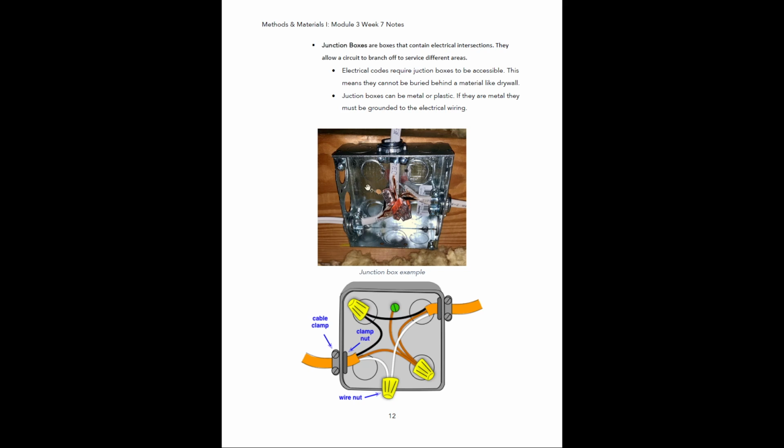So when you're all done wiring this up, you're going to screw a metal faceplate over this. Let's say one of these hot wires was exposed and was touching that metal plate. That is going to cause a hazard for somebody if they were to then go in and work on this metal box later on. If you're going to touch that and that hot wire was touching the metal but it was not grounded to the box, it would shock you. And that's really dangerous.